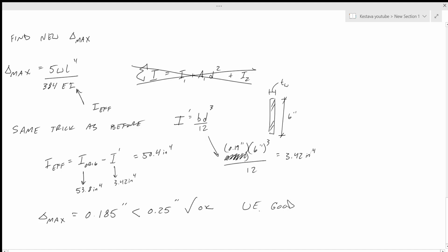We can tell that contractor, go ahead and make that penetration. Just make sure it's centered in the beam and it's at the center point, at the midspan of the beam. Otherwise, we're gonna have to run calculations again. So you really want to be strict with telling them the guidelines on where they're able to put that. You don't want to just give them free rein and say, yep, a 6-inch penetration can go anywhere, because it does affect the beam differently depending on where it is.